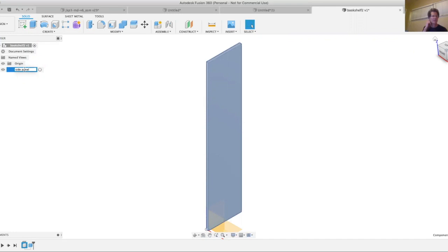I noticed in some of the tutorials that people put a description of the material and length in the part name so that it showed up in the cut list. But in the cut list or the parts list, there's also a description page. And I prefer to put it there. My reasoning is that I might come back and change my design. I do a lot of iterative design. I make it once, I look at it and go, that's too short and fat, so I want to make it tall and skinny. I'm going to go in and edit it later. And so I'll wait till the last step when I'm making the drawing to actually put that level of detail in for the parts list.